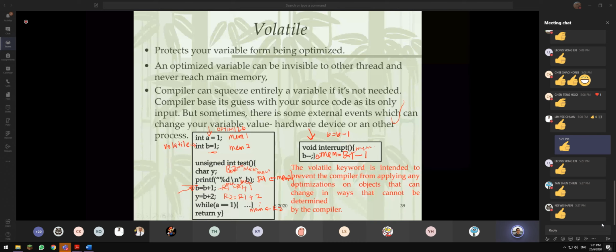You as a designer know which variable should be declared as volatile because you design the code. You know that something is in the interrupt, then you know that, oh, this is very important, I should declare it as volatile. No worry, as a student, you don't care because you are not using the paid version. You are using a student version. There's no optimization over here. So is it clear? Give me a thumbs up again.